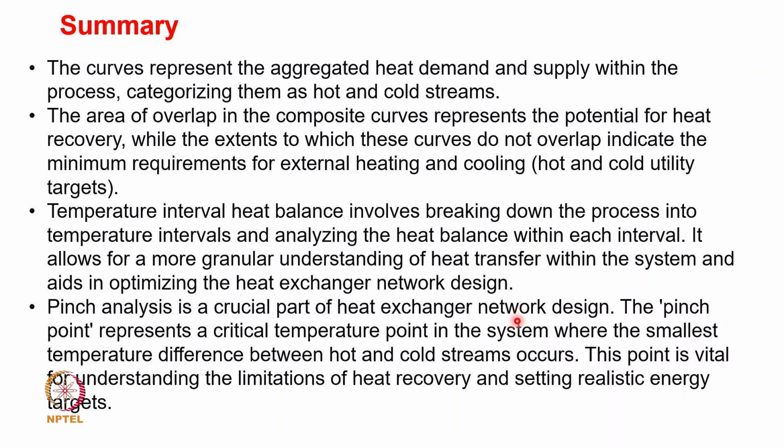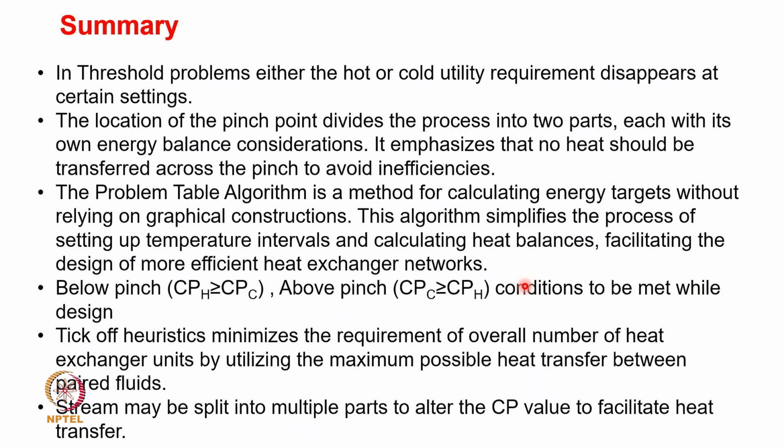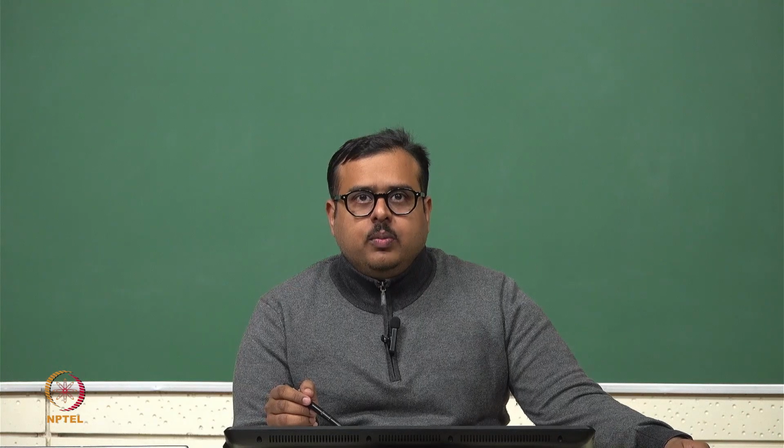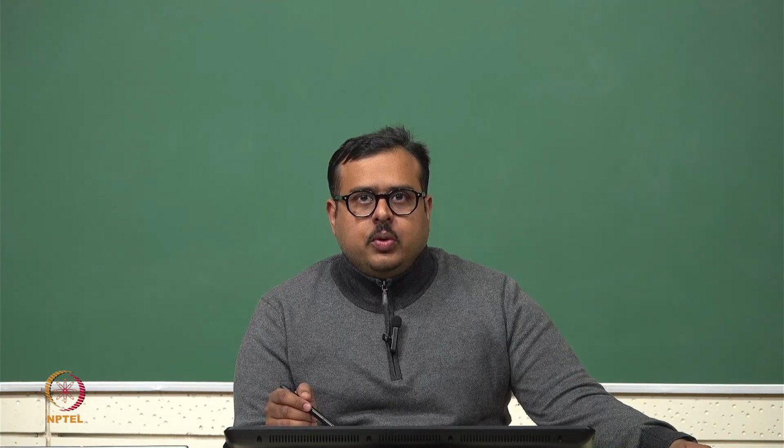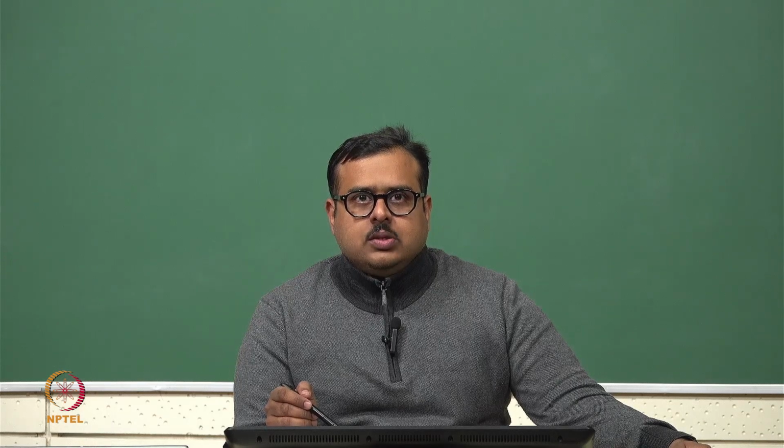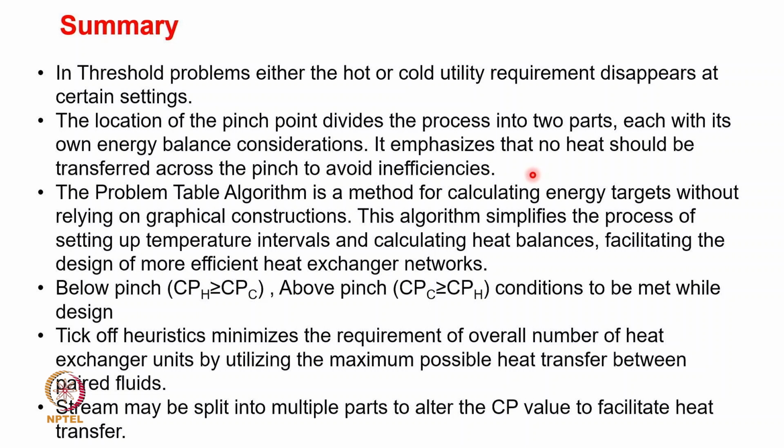This allows a more granular understanding of the heat transfer within the system and aids in optimizing the heat exchanger design. Pinch analysis is a crucial part of heat exchanger network design. The pinch point represents a critical temperature point in the system where the smallest temperature difference between the hot and cold stream occurs. The point is vital for understanding the limitations of heat recovery and setting realistic energy targets. We have seen threshold problems where either the hot or cold utility requirement disappears, and the location of the pinch point divides the process into two parts, each with its own energy balance constraints, emphasizing that no heat should be transferred across the pinch to avoid inefficiencies.